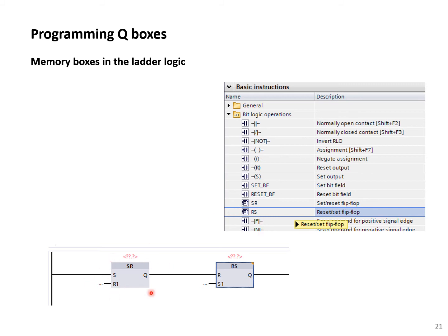In this one, you see that we have SR and RS boxes in series, and we have a set connected to the left-hand rail directly, and the reset in this case is connected to the Q box. So one of them should always have a contact or connection. The others are optional. We could have either that contact or not.